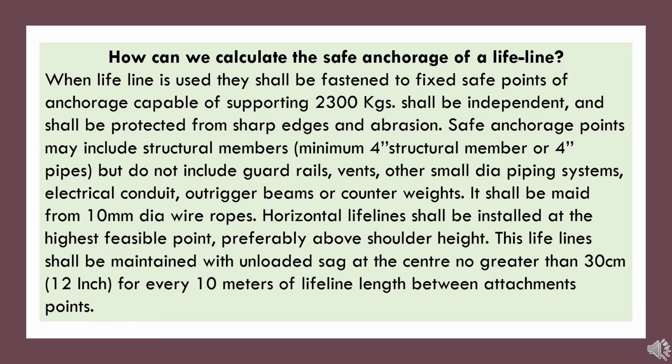It shall be made from 10 mm diameter wire ropes. Horizontal lifelines shall be installed at the highest feasible point, preferably above shoulder height. The lifelines shall be maintained with unloaded sag at the center no greater than 30 cm, 12 inch, for every 10 meters of lifeline length between attachment points.